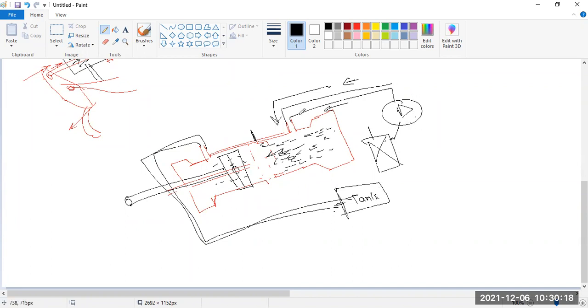So the pump is pushing due to the lever action of this spool valve. The pump is channelized to this side. This is the head side, H side, and this is the R side. So the head side is gathering this fluid, so it will push this piston, and the piston is going to the outside. But what happens if you change this channel to this rod side area? Then the pump will be connected in this way.